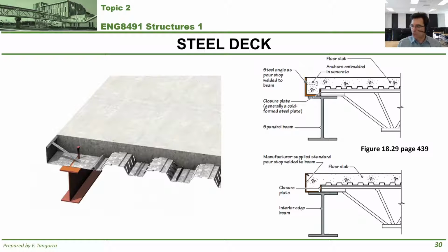Anyways, I was talking about pouring concrete and having pour stops. Specifically, what I'm referring to, if you look on the left, is this L shape that can be typically fastened to a beam or similar, and it basically stops the concrete from pouring over the edge of the deck, right? Because that's the whole thing about concrete. You have to tell it where it must go, okay? And I'm just pointing this out too because it will help you with your working drawings, right? Getting full marks.